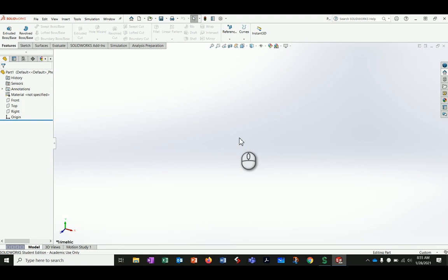So what we do is we can use surfaces, and I'm going to demonstrate in a minute. We can use surfaces to make organic shapes with this zero thickness. And then when we're completed, we can then give the object thickness. We can give it that third dimension. And we find that works very well inside of SolidWorks.